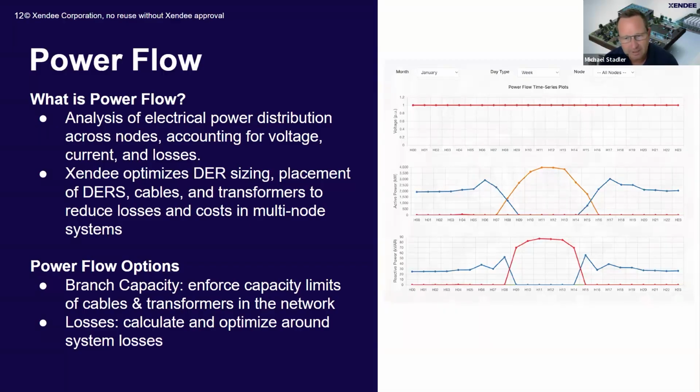So it's not really in the milliseconds, but for the design of the system from a thermal perspective, this is sufficient. And then later on, we move this anyway into the one-line diagram and can do a quasi-static analysis or a snapshot analysis for certain scenarios.